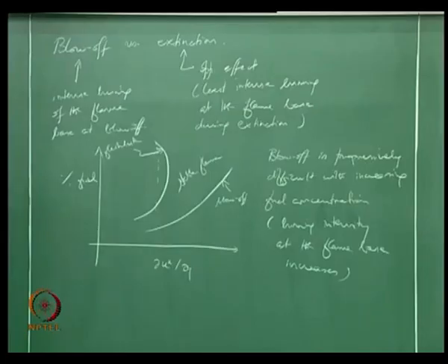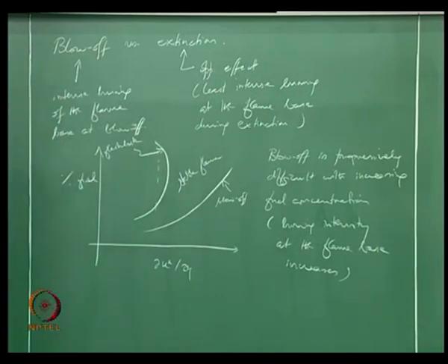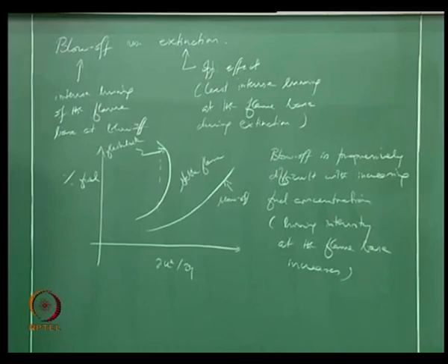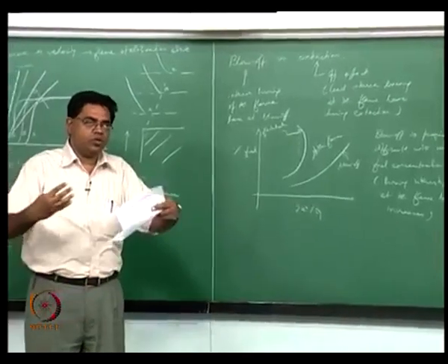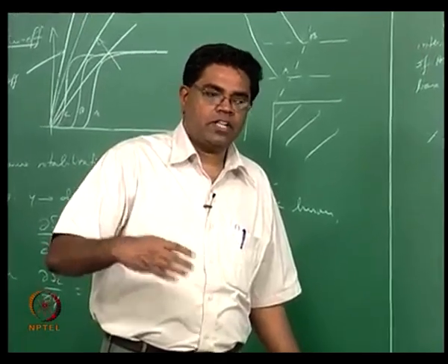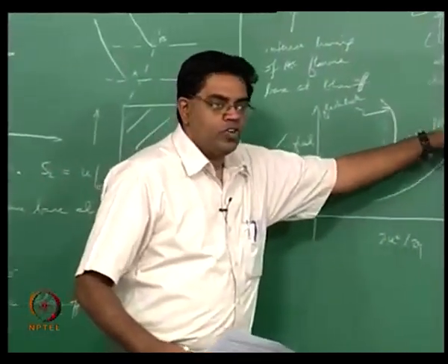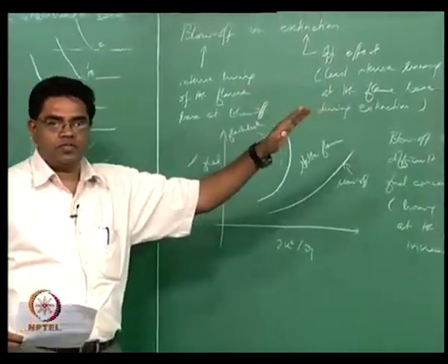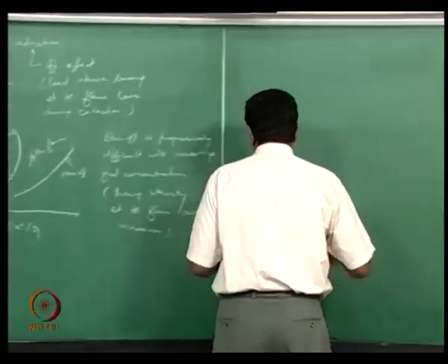There is another way of looking at this. Of course, the question that you have to ask immediately is, what if I actually burn this in an inert environment? Is it okay if I now have, let's say, a nitrogen ambience in which I have a reactant mixture that is coming out through the burner, right? What happens then? I'm going to allow for nitrogen to dilute through the sides regardless of whether it's fuel rich or fuel lean. Should I expect the blow off to actually be happening for fuel rich mixtures as well? Yes, sure enough, correct.